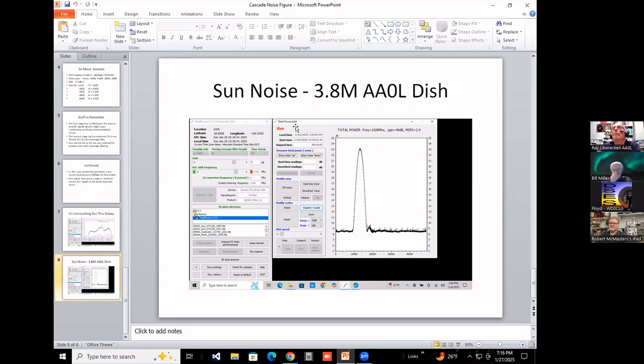And it's the total power program. And do you have the preamps in front of it, or what's the configuration? Yes, it does have a preamp right out at the antenna and about 30 feet of line coming in, maybe a little bit more. It is a Nuelec preamp that they sell. It has about 40 dB worth of gain with a SAW filter in the middle of it. In other words, 2 stages with the SAW filter, very similar to what I build down for the site. And it has a noise figure of about a half a dB and a gain of almost 40 dB.